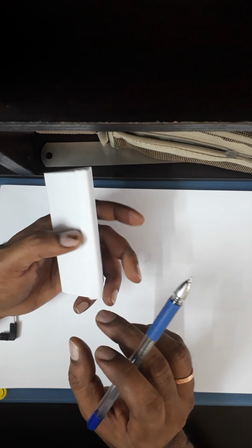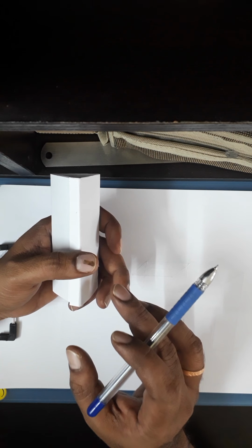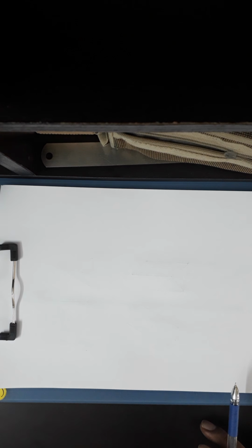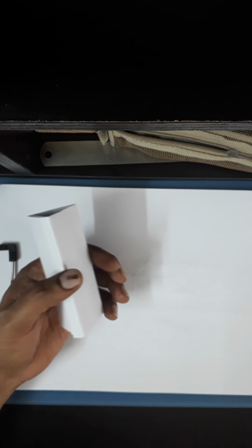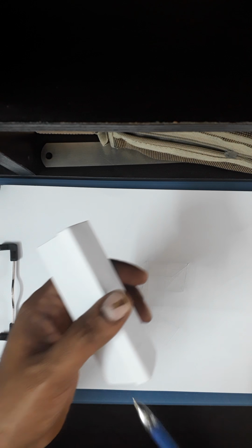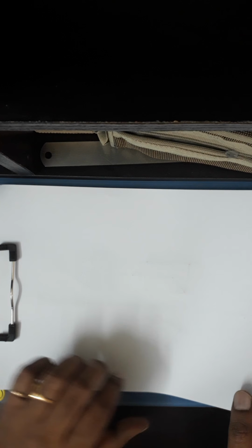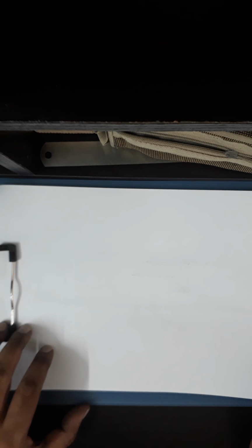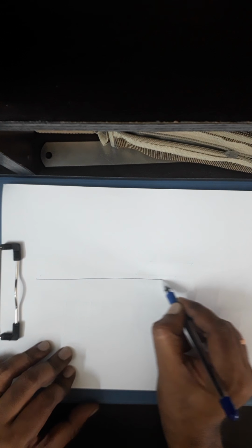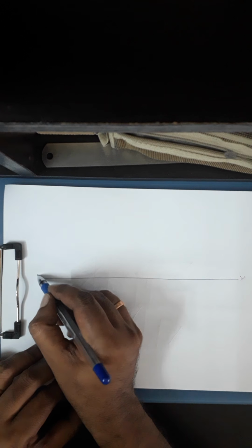So I'll go for the corner position now. Anyway, I'm going to have it resting on its base edge or resting on one of its base corners. In that way, I'm going to find the problems, okay. I'll explain the same thing now. Having one of its base edges in VP and the axis inclined to VP, the same condition as I did here for this problem, okay. In that case, we'll go for drawing and divide this into two parts, XY line, okay.